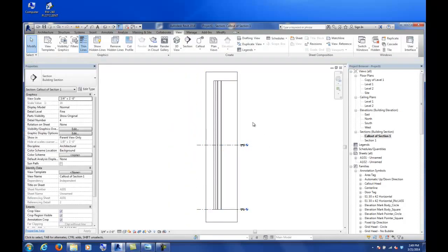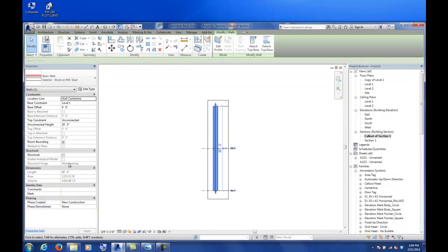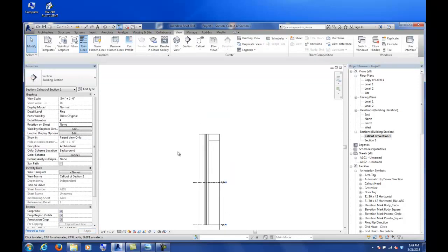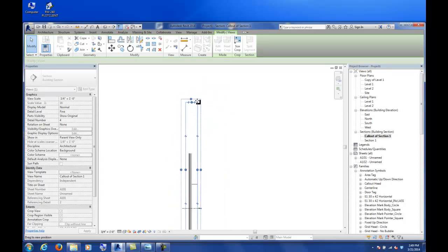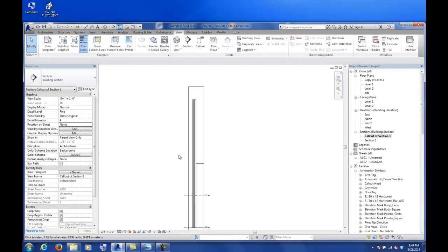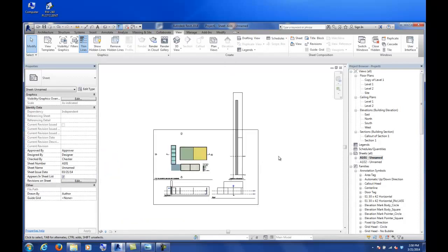The other thing is, let's say this wall section, I'm going to click that wall and make it like 40 feet tall. So let's say I've got this wall section, and the requirement is I need to really show this at 3/4 inch equals a foot in order to see the level of detail of this wall. But when that wall happens to be 40 feet tall, and I go back into my page, notice obviously that wall section is going off of the sheet of paper.